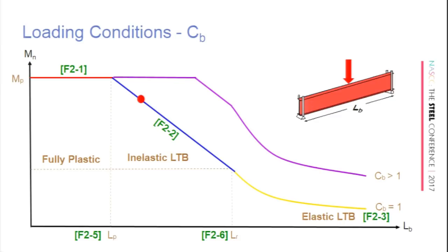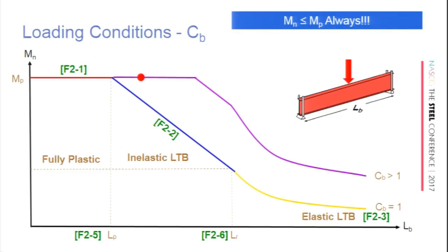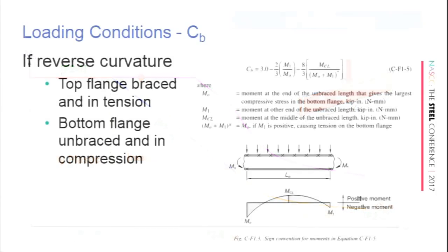And what does that look like in our curve? Well, if we happen to have some bracing provided, or a link between our support points, that falls a little bit less than L sub P, so we're in that inelastic range. We calculate our C sub B, and it turns out that we get a value of Mn above our M sub P. Should we use that value in just normal design, not in Perry's displacement-controlled experiments? Generally, no. We don't want to use that. We obviously have to drag that back down and make sure we do not go above the full plastic moment capacity of the cross section. This is where I could always catch my undergraduate students. I would hammer that home, and then of course on the exam they would forget and come up with a nominal moment greater than the plastic moment capacity.